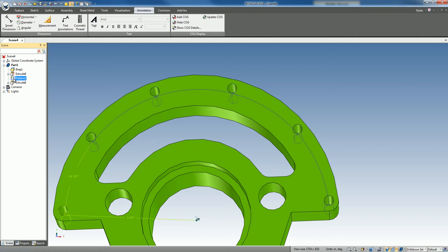If we need to go back, we can go back to the extrude, move it back, copy this around. We have this definition. We could delete this one out, copy this one, and make 3 pieces if we wanted to. So that's the benefit of having the features. We can make very simple modifications and maintain some intelligence to the geometry. But even in IronCAD, even if this is just a quick design modification that we need to get out the door, we don't care about that.